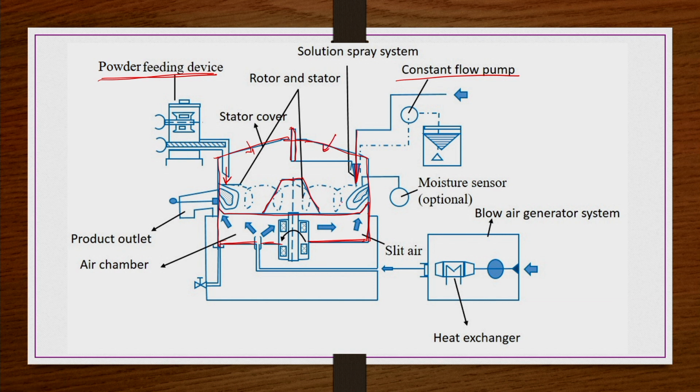When they are coming and this rotor is rotating in a specific direction, mixing between these particles and the binding liquid will take place. So the rotational speed has to be controlled. If the rotation is too high, the particles coming in will directly hit the walls and be centrifuged, or they may rotate as a rope wall along the container wall.